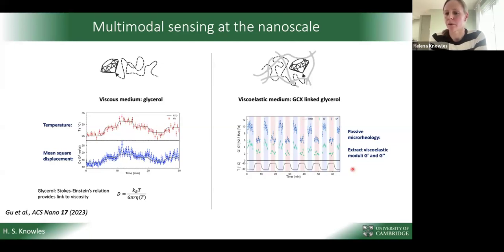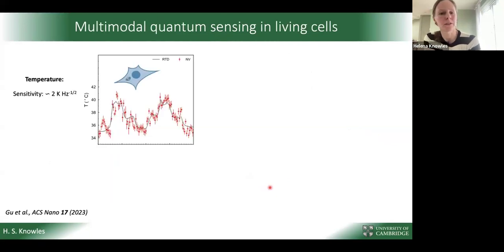So basically how liquid-like and how solid-like. And you can see the blue and red stripes here correspond to cold and hot. So we step the temperature of the chip between cold and hot, and we see indeed that these viscoelastic moduli step up and down. And so we see changes in the viscoelastic properties, as we would expect. So this works very well in model systems.